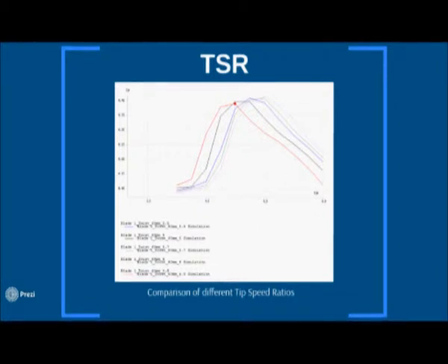The chord lengths were then recalculated for different TSRs and used to predict the optimum TSR, which would yield the highest power output for our blade. After having repeated the process for a range of TSRs, the optimum TSR for our blade was decided to be 4.8. Although higher TSRs were predicted to give a higher CP, the maximum rotation speed was taken into consideration in the selection process.